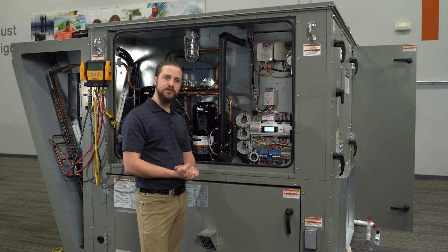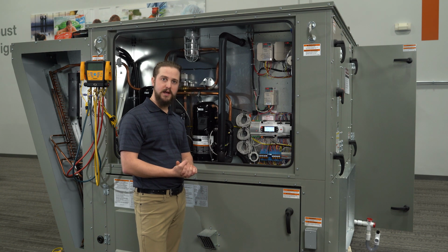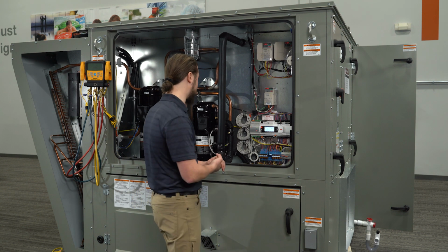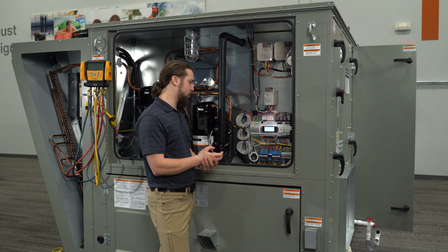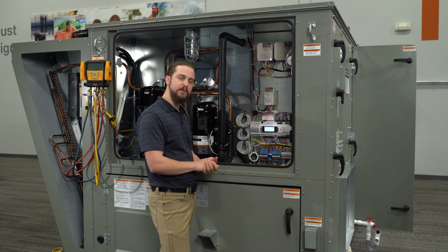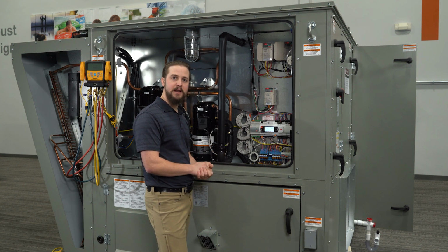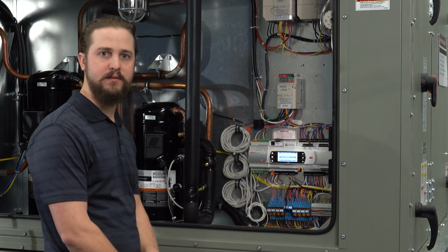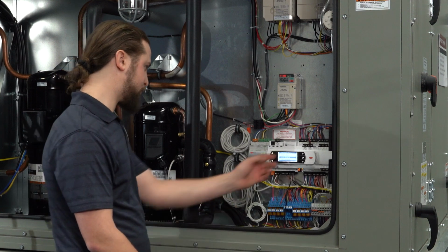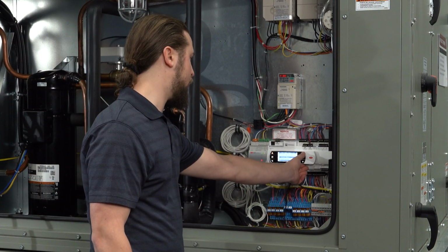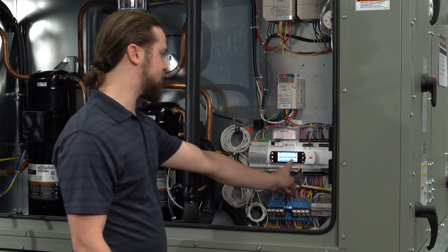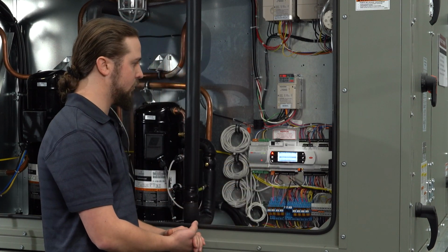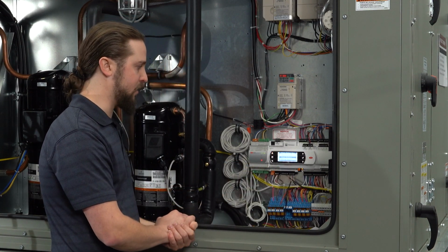Starting with low pressure trips, there is a way to look at your alarm history. So let's take a look at that first. To look at your alarm history and determine if low pressure trips have been happening in the past, first we're going to press the bullseye button. That'll get you into the main menu. We're then going to hit the up arrow until you see the alarm menu. We'll then press enter, and you'll see right here the alarm history.